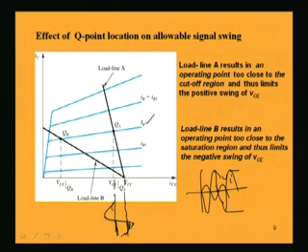Similarly, if we consider this load line, this is the operating point, what will happen is that in the negative half cycle, the operating point is closer to the saturation region. In the negative half cycle, this is the maximum collector current that can flow in the circuit. Its upper point is fixed by the load line, which is VCC by RC. You cannot go beyond this point. So, if we consider the negative swing from this DC value, it will be increasing, but it cannot increase beyond this point. So, this region will be cut off, but of course, the upper portion does not have any problem.